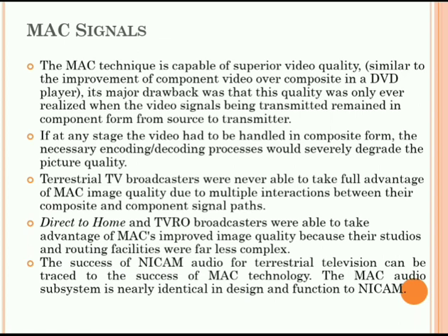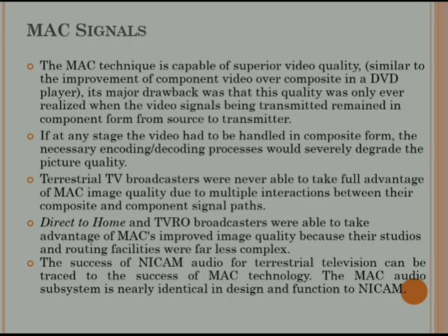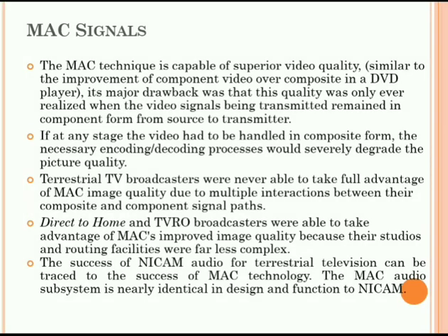Now let us see. The MAC technique is capable of superior video quality. It is similar to the improvement of component video over composite in a DTV player. Its major drawback was that this quality was only ever realized when the video signal being transmitted remained in component form from source to transmitter. If at any stage the video has to be handled in composite form, the necessary encoding and decoding processes would severely degrade the picture quality.